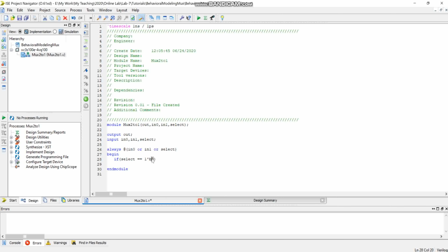So this is the binary digit that we want to write, but in order to write this, we need to specify the number of bits and its type, right? This way we can also write hexadecimal numbers, octal numbers, and decimal numbers. So we need to specify the number of digits, the type, and then the digit itself, right? But in this particular tutorial, we will restrict ourselves to binary digits.